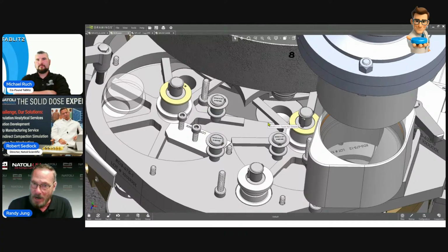Powder that comes around in your recirculation band re-enters the feeder, goes through the metering paddle, passes over to the delivery paddle. It becomes densified again. And if I have big tablets, 2 grams, you don't see as big of an impact of this. When I have small tablets, 300 milligrams and below, 400 milligrams and below, this densification of the powder actually causes your RSDs to fluctuate quite a bit.